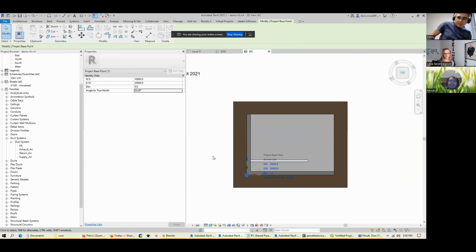Stuff already done in a survey drawing, as well as what I call a site drawing. So I actually differentiate between the two. I say you should ask for two things from your surveyor. You should say, can I please have a site survey, which is the way surveyors see the world, in eastings and northings and grid north up the page. And then you should say, can you also give me that DWG, DXF, whatever it is, as a site drawing? And I want you to transform it to small coordinates. I want you to do the rotation so that project north is up the page.